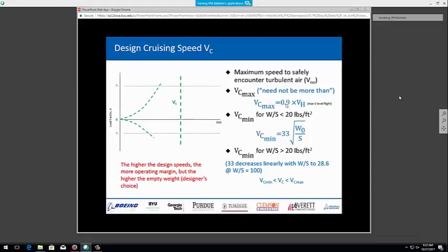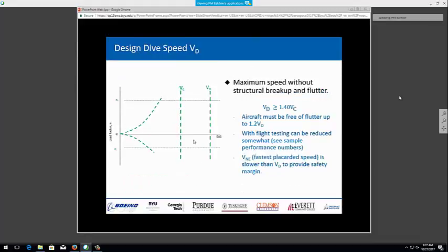I've seen things break on the backside too, inadvertently. Somebody got upside down and collapsed their wings also. So I hope you don't do that. For initial flights: minimum weight, minimum battery, no payload. Get the weight down as low as you can, and that will begin to tell you what you can do. Then you begin loading your airplane up to the full conditions that you designed for. So that's the VN diagrams.